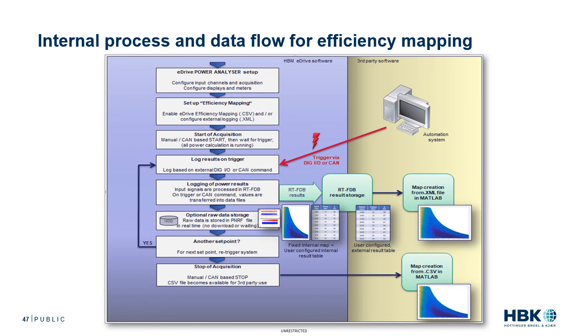No problem. Very easily done. When it does get that trigger command, it then performs the acquisition, which can be however long of an acquisition you decide it to be, and it logs the results that you've laid out in the setup, so the torque, the speed, it calculates the efficiency, and then starts to begin creating that efficiency map.